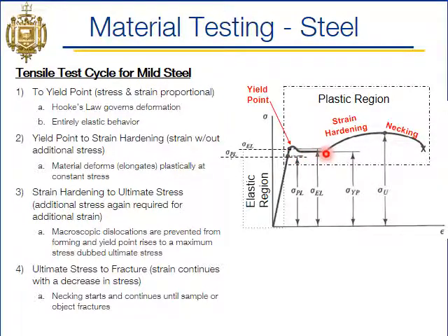In this region of our tensile test, what's happening is the steel grains are sort of realigning and reconfiguring because of the amount of stress that they have felt. And then eventually they get realigned and reconfigured, and the steel begins to take more stress. So we call this region the strain hardening region. You can see right here there is more stress being taken than at our yield point. So the material actually got stronger through this test, which is very typical for steel.